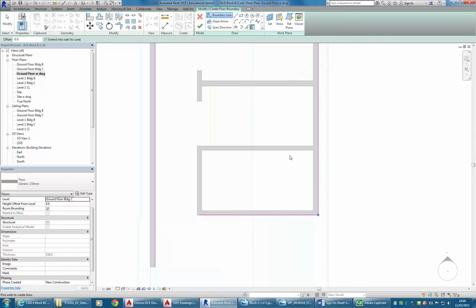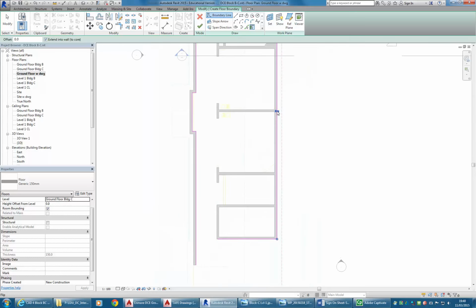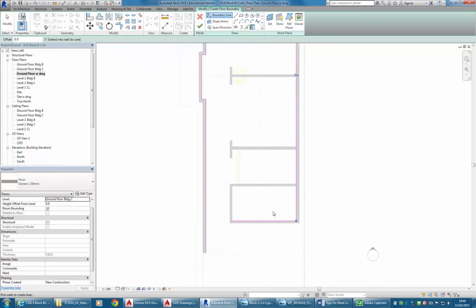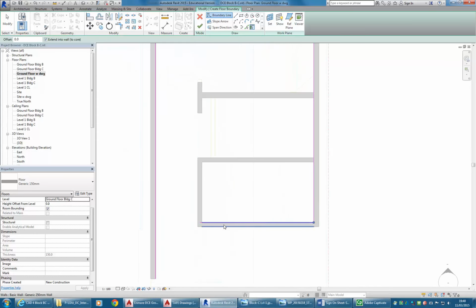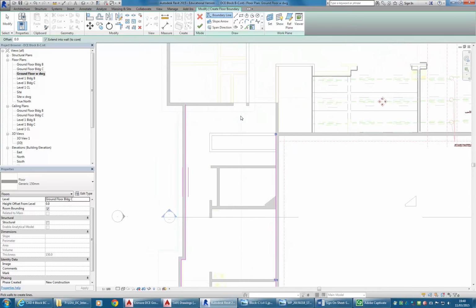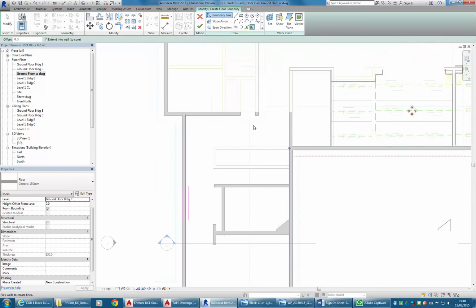And again here, where I'm choosing the outside wall, it's gone to the outside of that exterior wall, and I want it on the inside edge. So when I flip it, if this line changes, that's okay, because I'm not really worried about that line. I'll redo it anyway later. So now I've got the transition area where the floor probably stops in line with the ramp here.